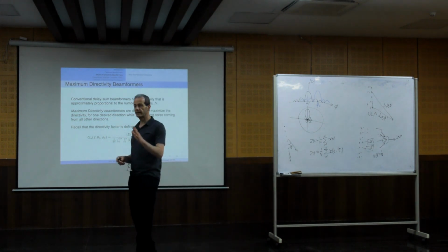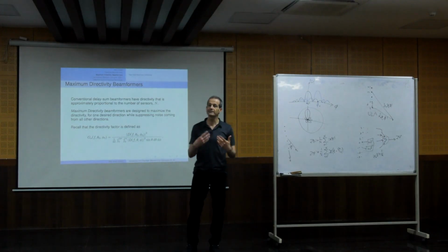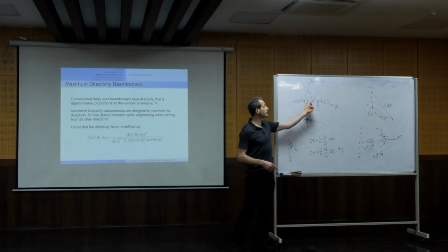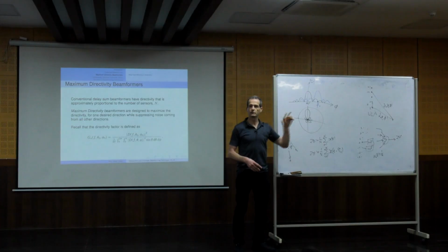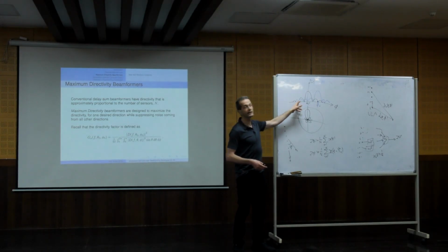So when I said that for high frequencies we don't want to distort the signal like a low-pass filter, it's enough that the beam width will be constant. So you don't want to add more constraints if they are not necessary. But if it's important to keep the null, for example, you know that the null for a certain direction depends on the frequency.